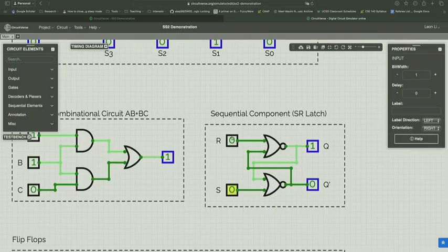But take a look at this condition and try to remember it. Both of the inputs are zeros, the Q output is a 1. Now take a look at this. Both inputs are zeros, the Q output is a 0. I did some flipping of the input variables, and now I get a different output. The output depends on not just the current inputs, but also what has happened before. So depending on what happened before, under the 0 input, I could have a 0 at the output, or I could have a 1 at the output. And that is the definition of a sequential circuit.